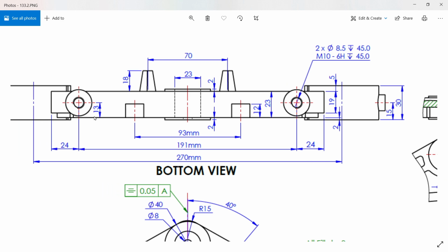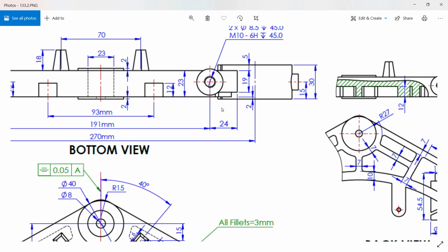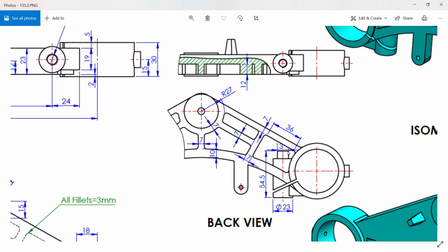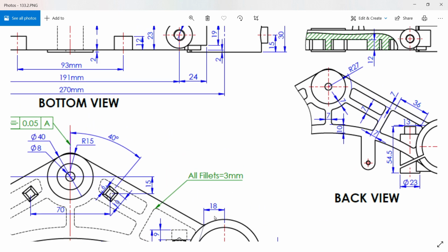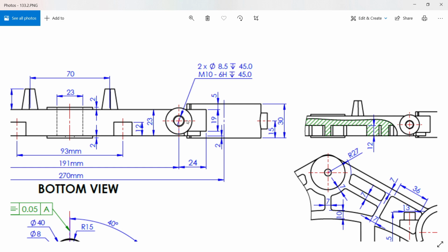191 millimeter, and this is 13 millimeter away from the bottom face. This is the bottom face. Then if you saw, there is one more extrusion, 13 diameter, and this length you will find here 9 millimeter, but this is after the cutout of this. And the back side also has a hole, machine tap M10, 45 millimeter long, or depth is 45 millimeter.